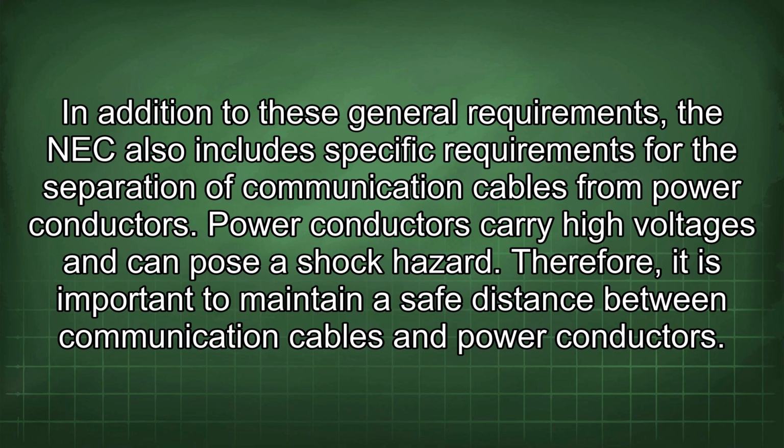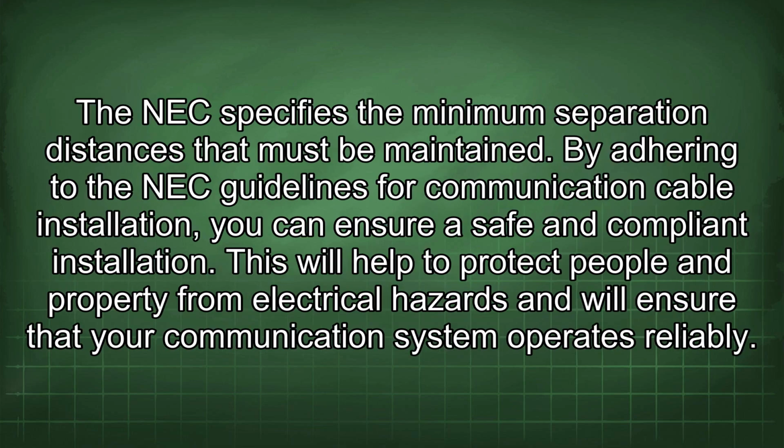In addition to these general requirements, the NEC also includes specific requirements for the separation of communication cables from power conductors. Power conductors carry high voltages and can pose a shock hazard. Therefore, it is important to maintain a safe distance between communication cables and power conductors. The NEC specifies the minimum separation distances that must be maintained.